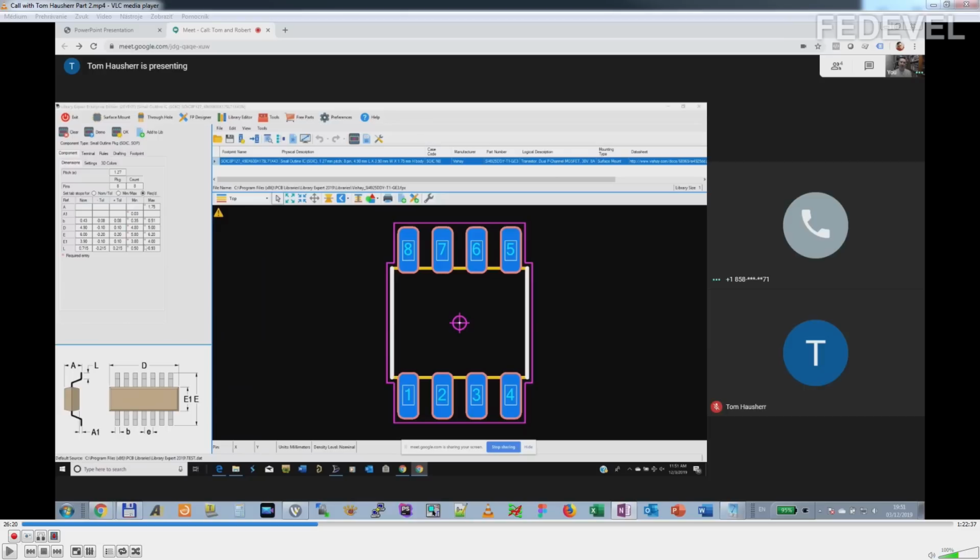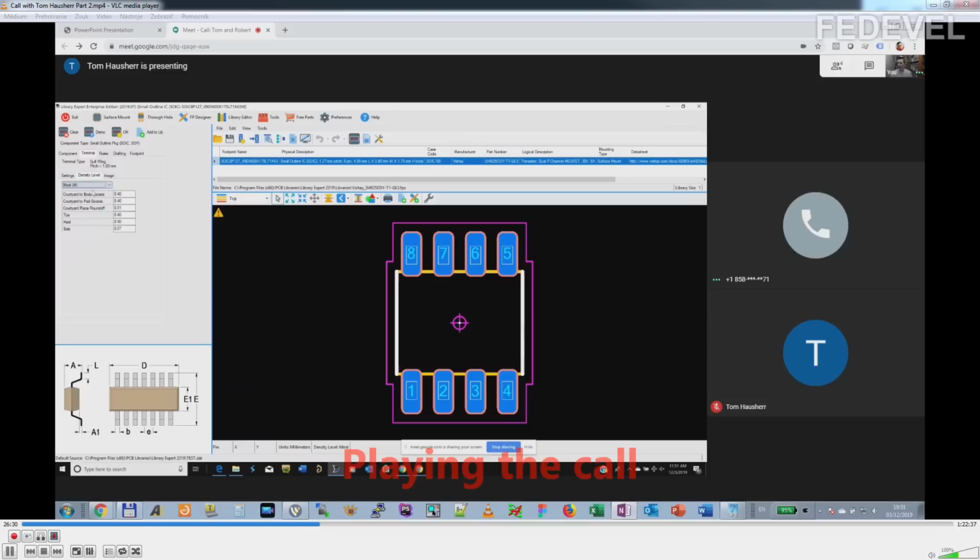So, very simple question: why are there three different densities? Well, you can say the top density level, I can say most here, and it gives me a bigger toe, a bigger heel, and a bigger side fillet. That's primarily, I would say, for the highest amount of solder volume that you could put on a pattern, for maybe military applications or satellites. It doesn't have to be weapons. Weapons in space, and maybe medical, where you can't fail. So it's reliability.